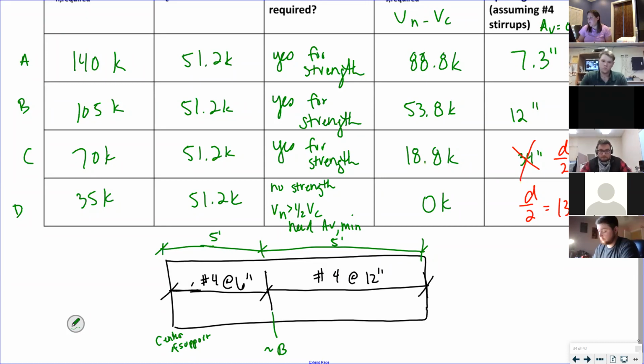And then when your shop drawings come back, I mean, 6 inches and 5 feet is nice, but when it's like 8 inches or something awkward, they'll say, okay, 5 divided by 6, where they're counting bars, and you decide, okay, did the detailer count the number of bars, and then they just shove them in there and about right, you know.